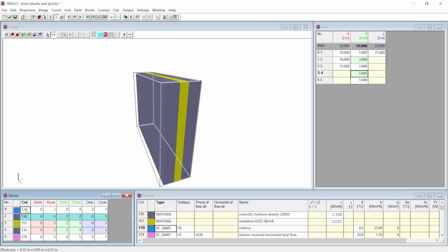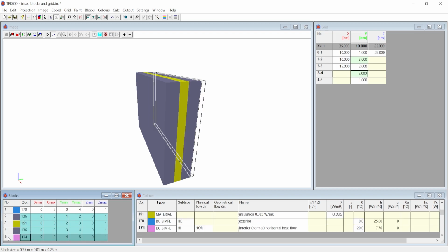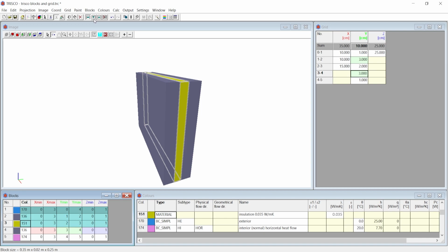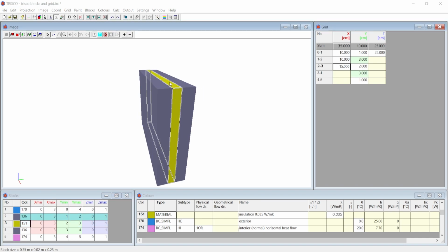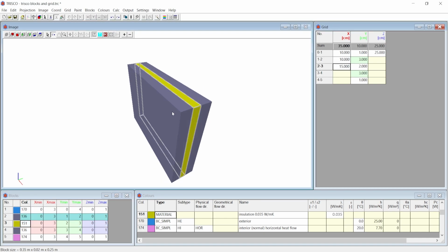You can hold Ctrl and click on blocks to select multiple blocks and perform a similar operation as before to move them on top or bottom. If you select by holding Shift, you will select all blocks in between in the selection. You can deselect the entire selection by clicking the Deselect All icon. Lastly, you can also select all blocks on top or bottom of your selection by choosing Switch Selection upwards or Switch Selection downwards.